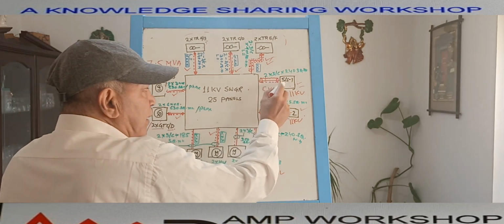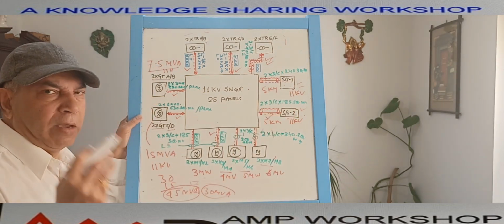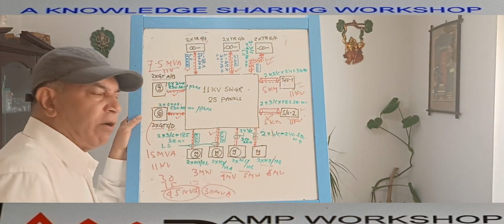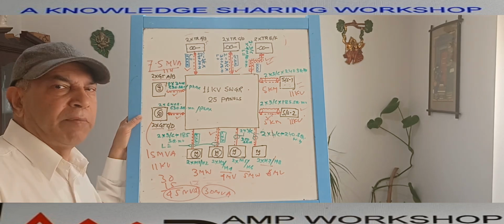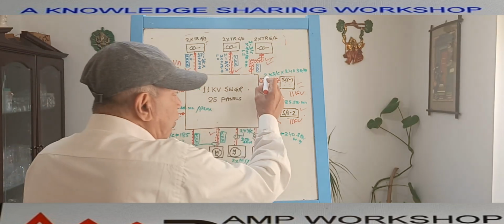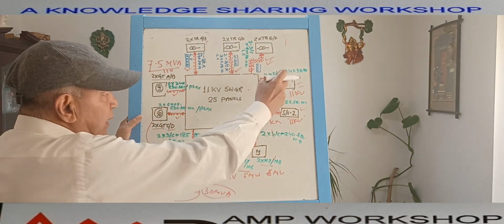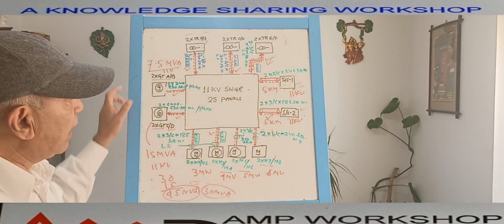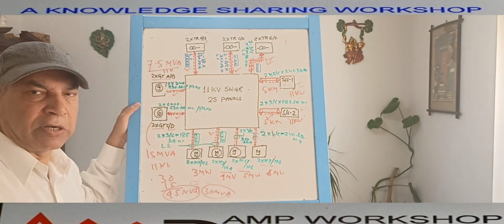Each substation is receiving 2 cables, because with subsea cable, though only 1 power cable is required, we always put 2 cables, because if 1 cable fails then the other cable will be there. So that's why 2 cables are considered. So these are the various loads we are representing around the main equipment. Then each equipment is connected to a power cable.